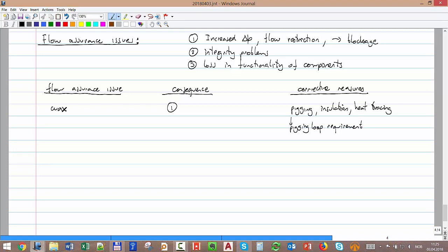Okay, remember, if we don't have a place where we can send and receive the pig, we have to make it round. We have to make it the same place you receive and take, and that's also very expensive. And we have also some chemical inhibitors that work, but sometimes you need high quantity. They are expensive.